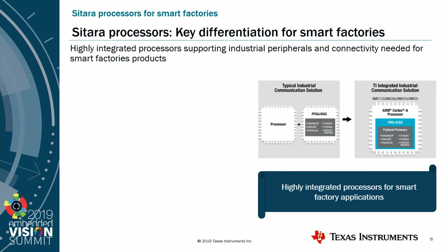Sitara processors are highly integrated processors which support multiple industrial communication protocols on one platform. Traditionally, the problem was solved with the help of an FPGA. So there's a processor to do the main task, but the communication protocols, since there is a wide variety of them, were solved through the FPGA. Sitara processors brought them together in one single solution in a platform which supports real-time communication protocols for all